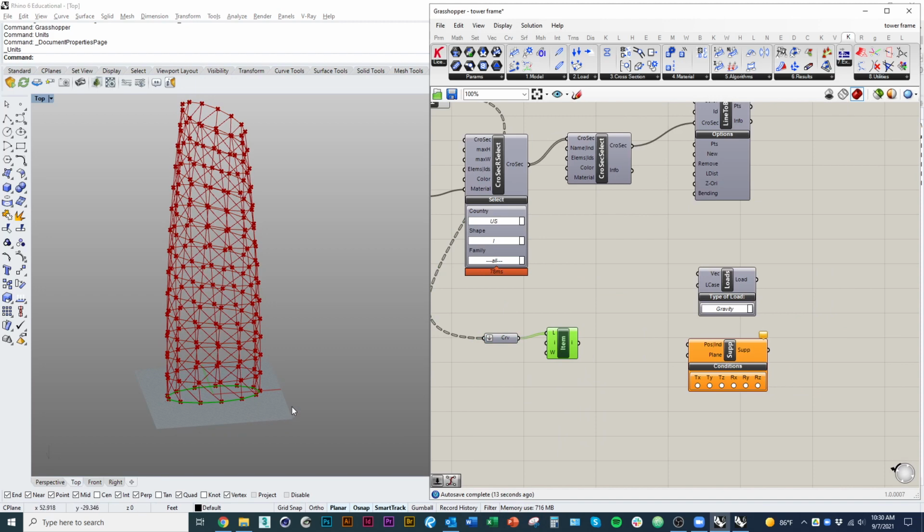And now I just need to return all the points along that outline. There's a couple ways, I can go explode, or actually, control points is the better option. Here we go, control points. If I plug that polyline into this component, it should give me all of the control points that define it.